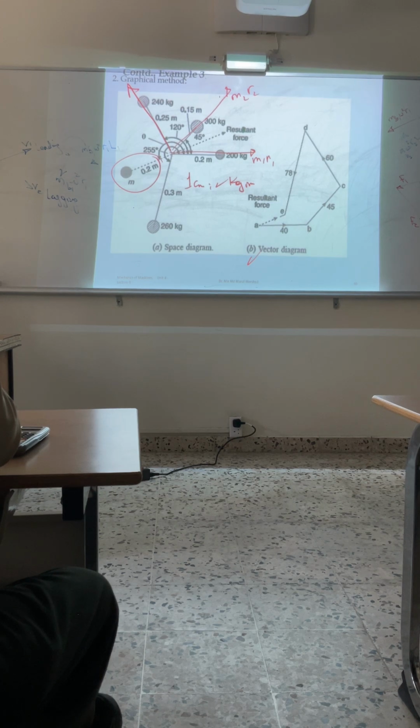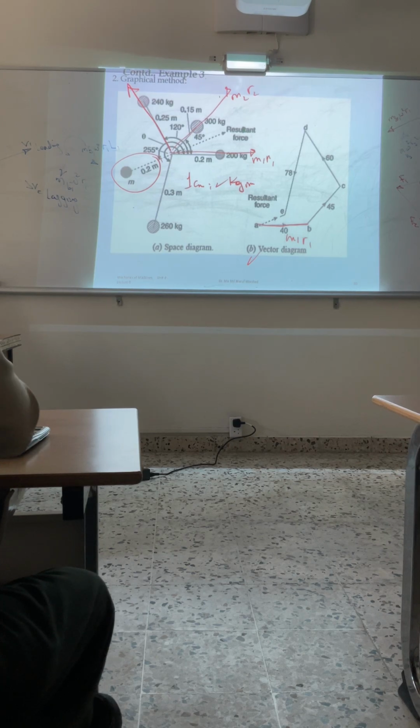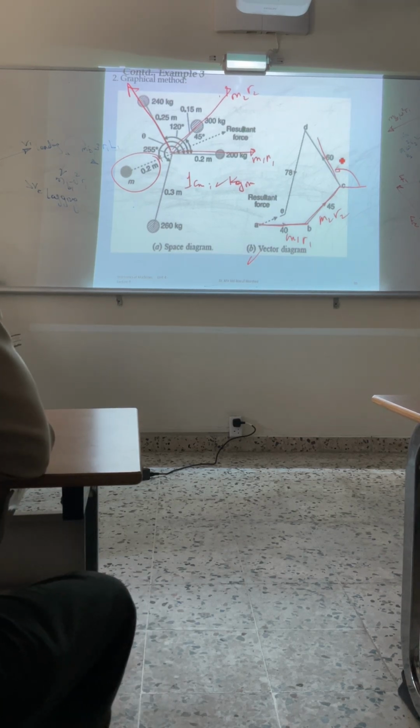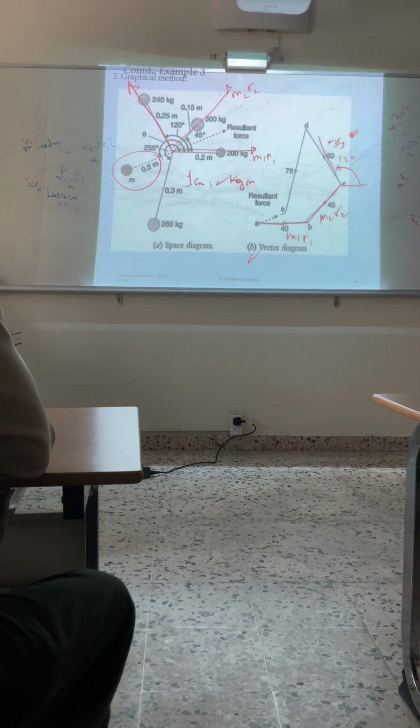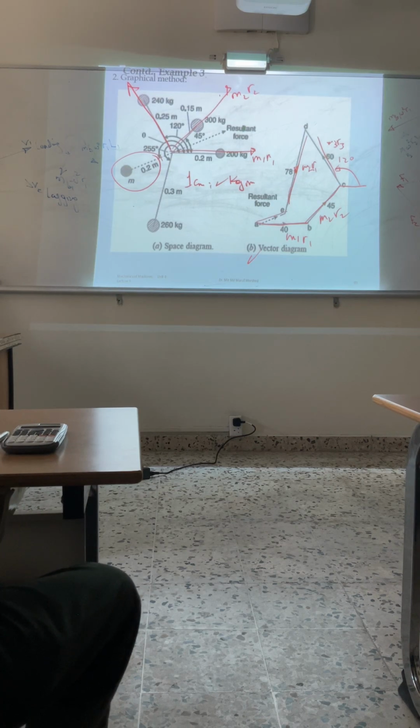I will explain. Now, this is M1R1. This is M2R2. This one, of course, this angle is how much? This is 120, right? Yeah, this is M3R3, and then this is M4R4. And then to claim that the balancing mass is added to make it in complete balance, this means that your balancing mass should be acting with a force in the opposite direction. No, this is incorrect.